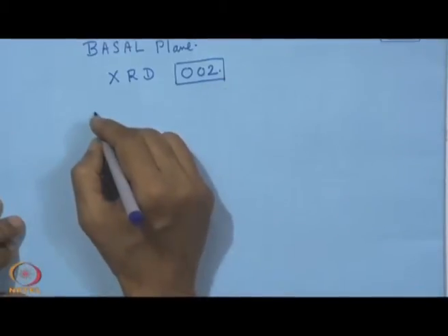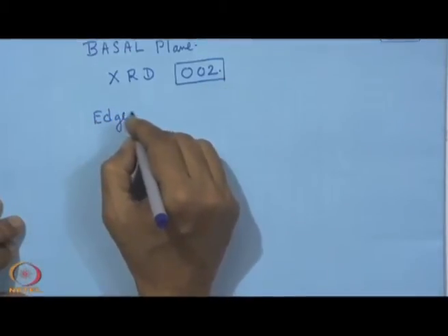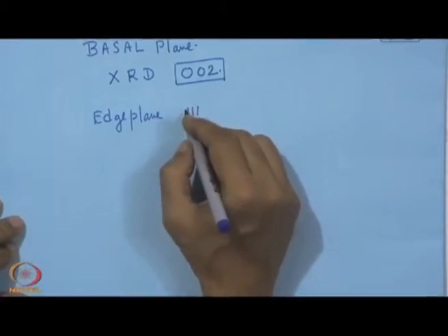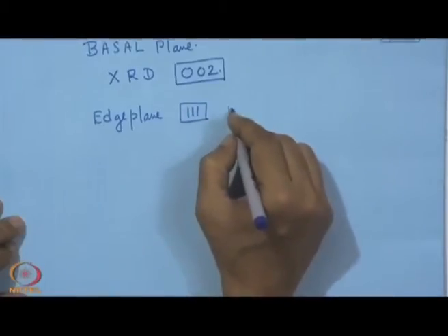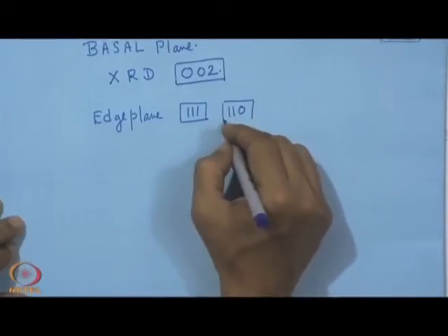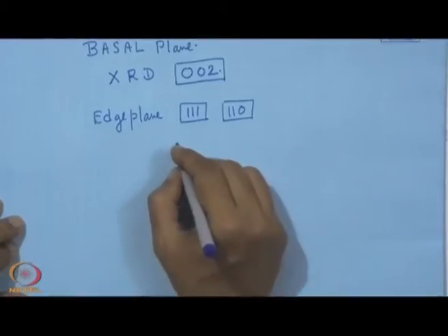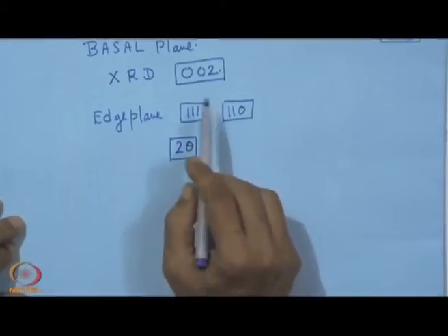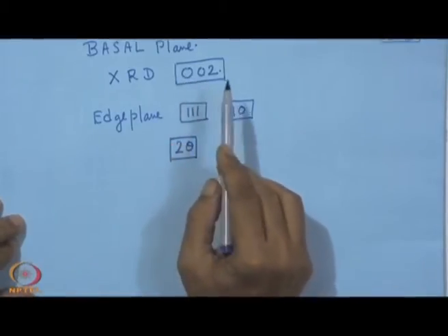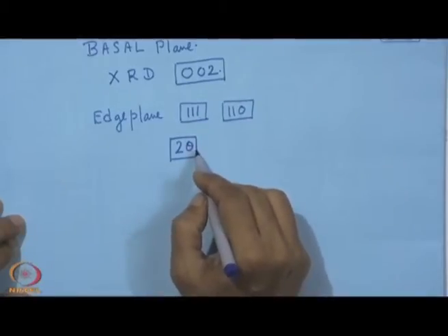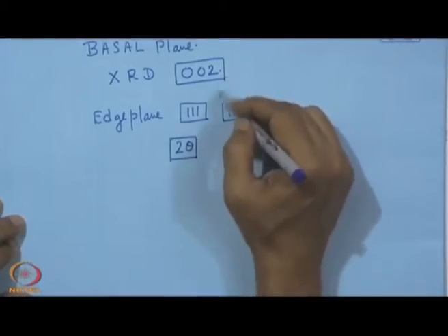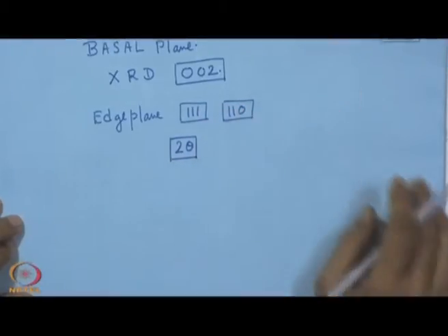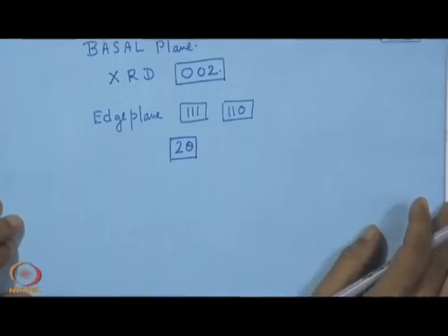It can be H plane, and in that case the peaks come from this 111 or 110, and for that we have a definite angle 2 theta. From the standard XRD corresponding to this MoS2, we can find out the value of theta which corresponds to this 002 or 111 or 110, and from that, concerning the quality of the coating, we can